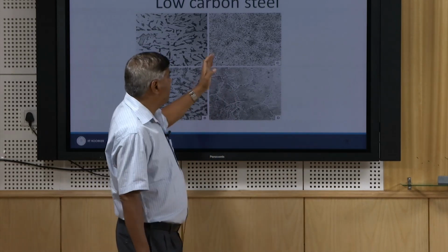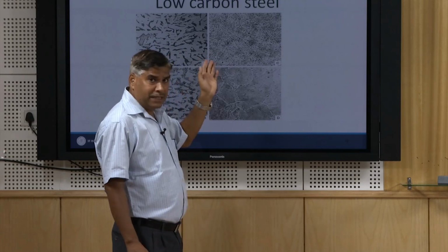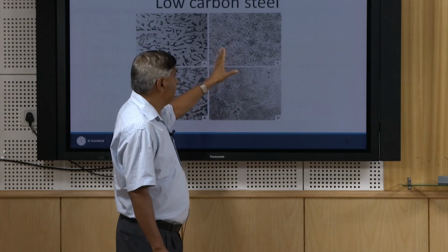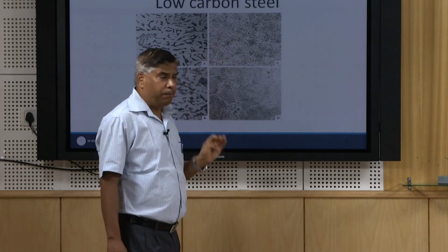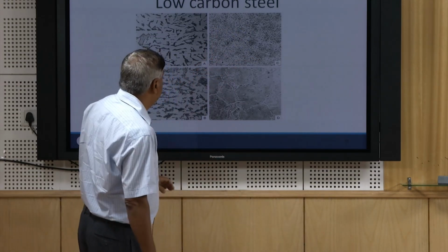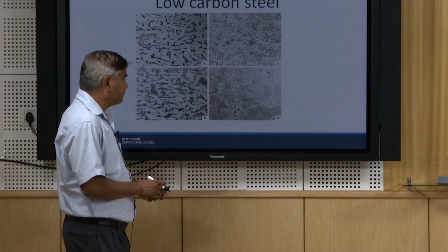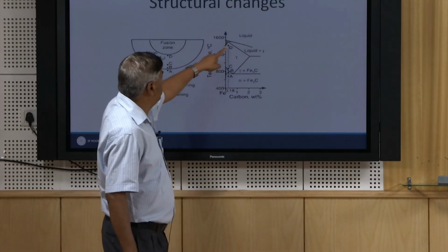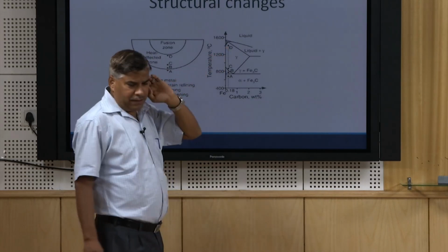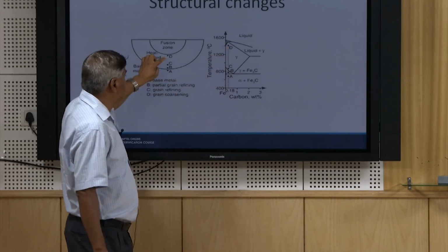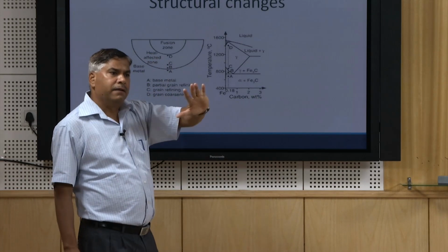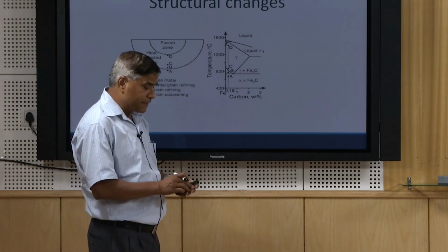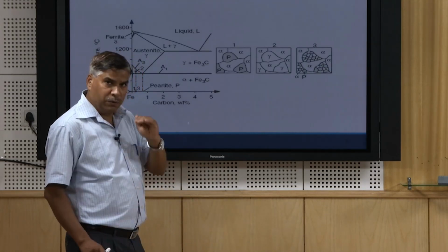During the subsequent cooling phase of the weld thermal cycle, it will be promoting a fine pearlitic grain structure. And point D is at this location, very close to the fusion boundary, and it is heated to a much higher temperature for a longer period. That is why it experiences grain coarsening, very coarse.